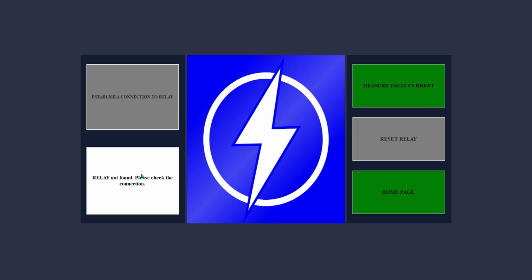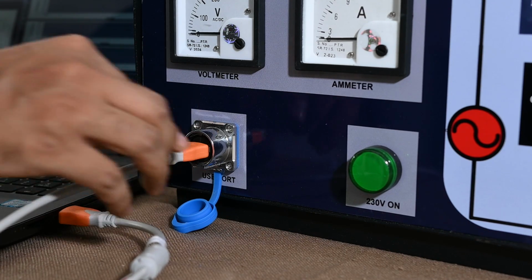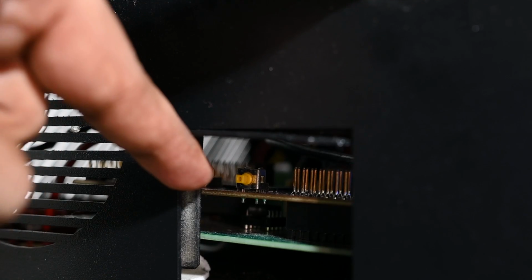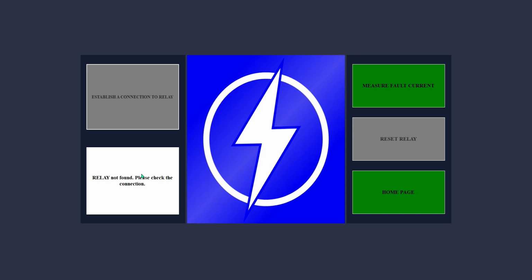This usually happens due to one of the following reasons. First of all, the USB cable is not connected, or the reset pin on the relay kit is not pressed. Ensure the USB cable is properly connected, then press the reset pin on the hardware to initiate communication. Now I verify the USB connection, but the establish connection button is still inactive.